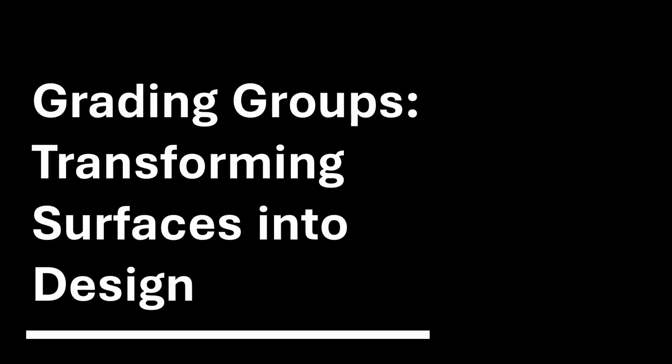And just as surfaces provide a mathematical model of the land, grading provides a mathematical model of its reshaping. In modern software like Civil 3D, grading is organized into grading groups, collections of related grading objects, slopes, pads, daylight lines, and feature lines, that together define a proposed modification to the real world. But before we get too technical, let's unpack some of the concepts behind grading itself.